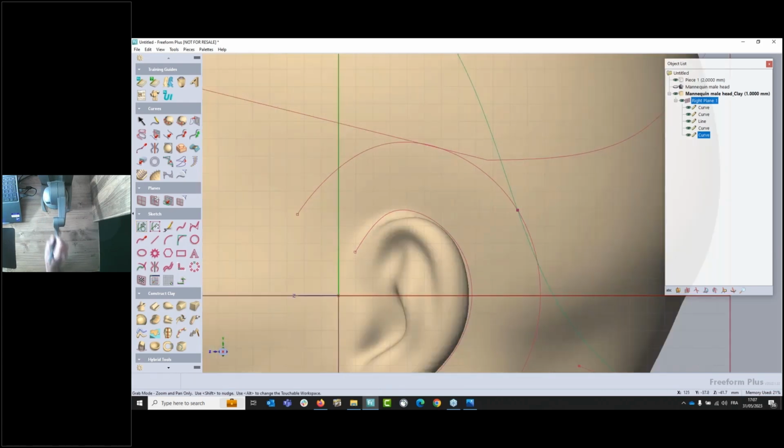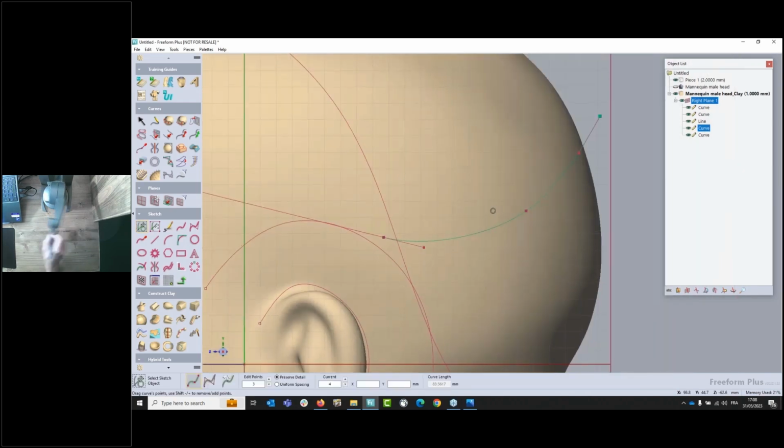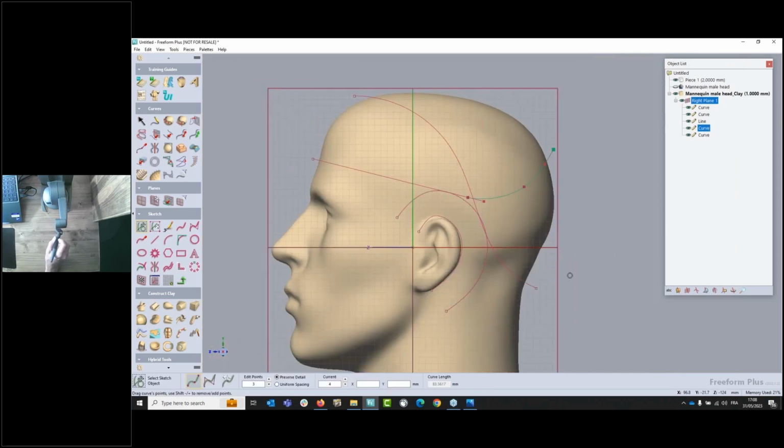Here, I don't want to have an angle between those two ones, so I would select this curve and I can move the tangency. And I will be tangent to my line. The line will become green highlighted. And with the device, I'm locked on the tangency direction. My curves are looking good.